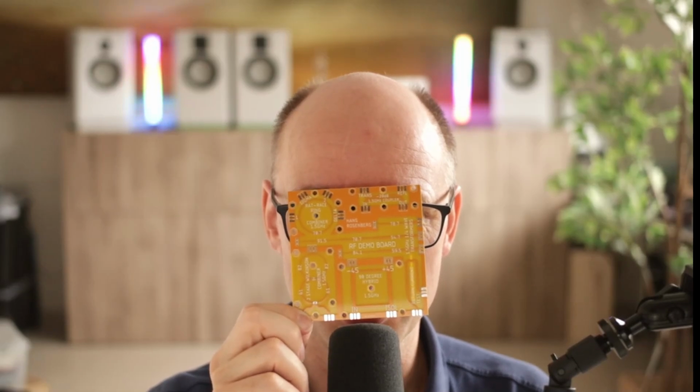Now, as I was filming, this board was delivered to my house, and this is the board that I'll be using for my coming 4 or 5 YouTube videos. It's all RF building blocks. It contains a rat race ring at 1.5 gigahertz, a 2-stage Wilkinson combiner at 1.5 gigahertz, a 20 dB 1.5 gigahertz directional coupler, a bunch of quarter wave transformers, single stage, double stage and triple stage, a 90-degree hybrid, and an extreme return current experiment.